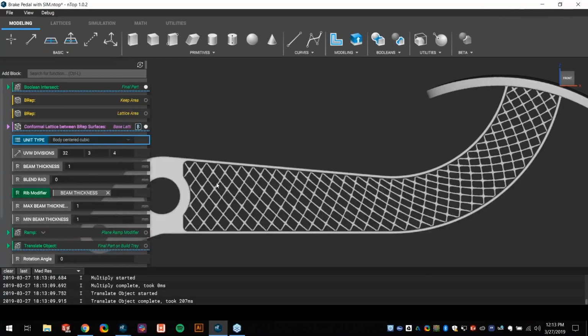One of the main issues that we see oftentimes with additive manufacturing and using lattice structures is this interface between the lattices and the skin is a weak point. It's a failure point. You have stress concentrations, you have sharp angles, and oftentimes that's where your part's going to fail first. Now, the way to remedy this is we actually want to drive a blend, or as you may call it, a fillet in other software, to give it sort of a rounded geometry so you can alleviate some of that stress concentration.